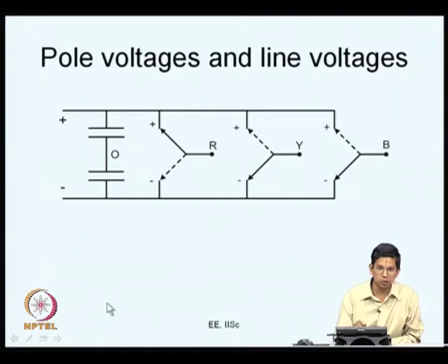We have considered two situations here. One is the inverter feeding an induction motor. The other is it is connected to the grid. The line side is connected to the grid through inductors. So, both cases have been considered, one is a motor drive case and the other one is a grid connected converter. Both the cases we have considered and we know how to calculate the fundamental current and harmonic current based on the fundamental voltage and harmonic voltages.